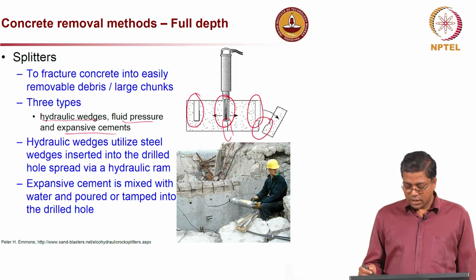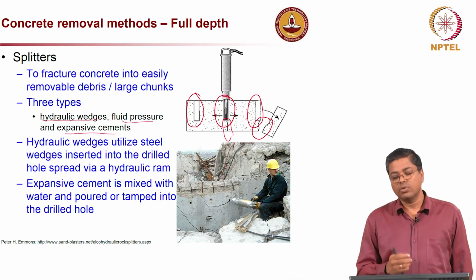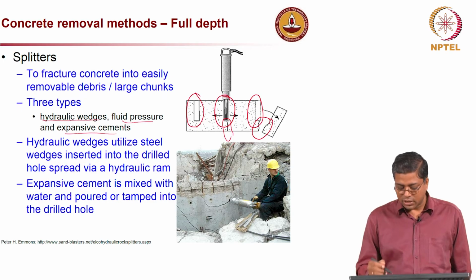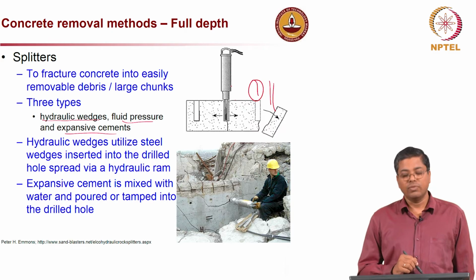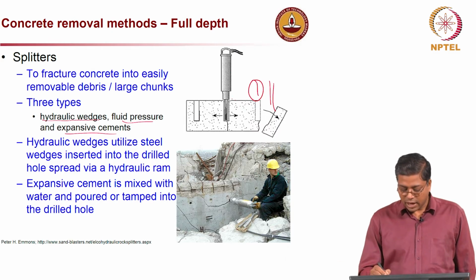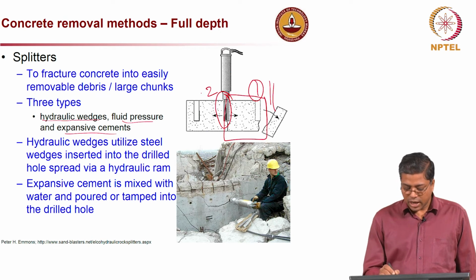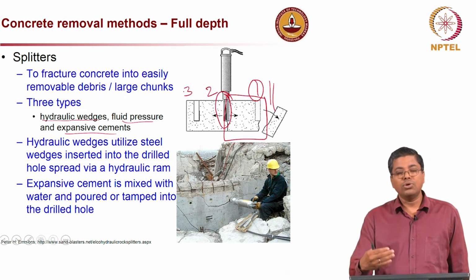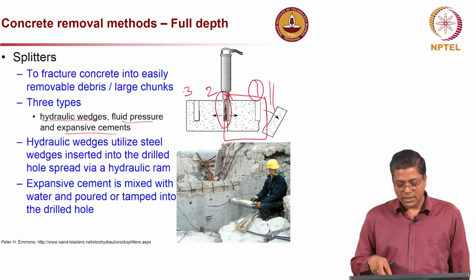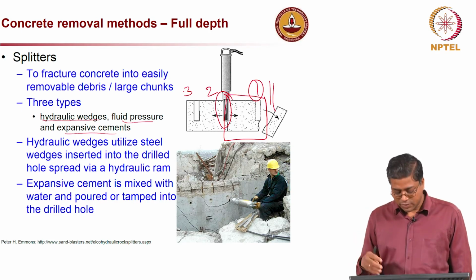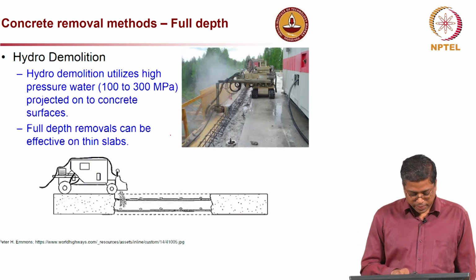And in this, the sequence in which you apply is also very important. For example, in the case which I am showing here, if the slab is ending here, then this could be the first hole which we need to do, and then split it, and then come here, this is number 2, and then we will remove this concrete and then come for the next. So you have to see how you progress. You cannot start from the center of the slab; you have to start from an edge, which will make the job very easy. Okay.